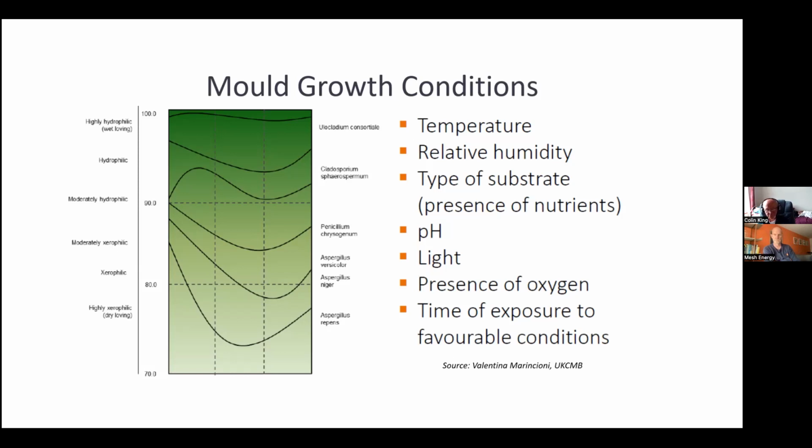What you need to do is, when you're looking at diagnosing rising damp, it very rarely ever is rising damp. What you usually find is it's lateral penetrating damp caused by ground levels outside or internal finished floor levels, which are destroying the equilibrium of the structure. And then through capillarity, the moisture is being pushed up the structure, because the smaller the hole, the higher that water will raise up a structure, which is why clay bricks and lime mortar, which has got very small voids in it, through capillarity, allows moisture to rise up. It's diagnosed as rising damp.